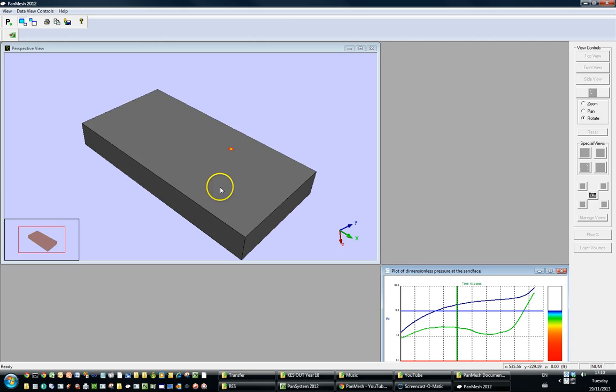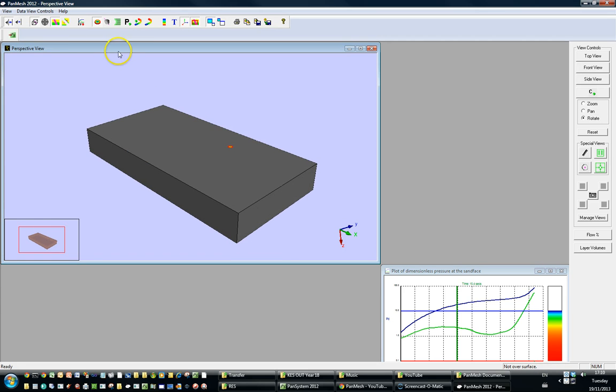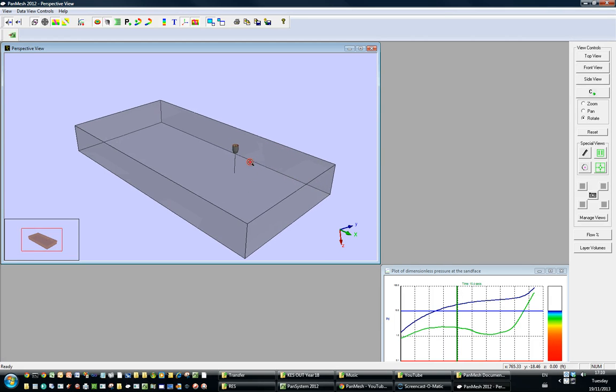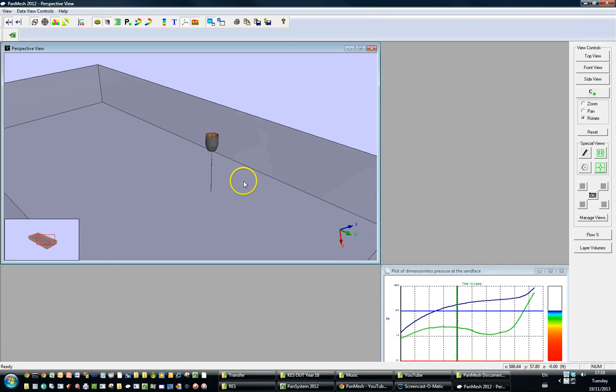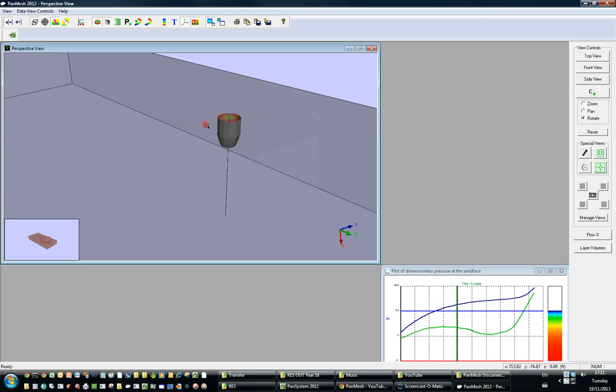What we might do is, again, as in the introductory video, we would click on isosurface, which shows us the radius of investigation, and we'll zoom in a little bit. You can zoom in by holding down Shift and using the right mouse button and dragging forward and backwards.